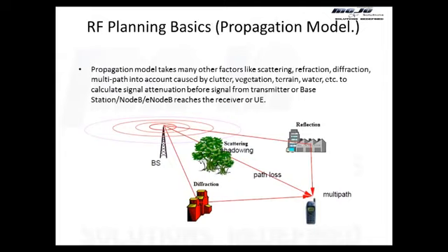There are multiple base stations in the neighbor vicinity of each other, so what will be the signal level from each of the base stations? There is a lot of theoretical work being done, and it is a work in progress to this day. For example, AT&T have a project called the suburban project or rural project. They bought a new propagation model and integrated it with their planning tool, which is ATOLL or ASSET, and they use that propagation model to predict the signal level more accurately.